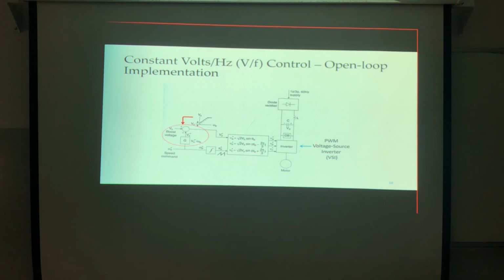With the actual output. We are giving a certain reference. Yeah? Now, if I need to control the inverter, I need to generate a reference signal. And any reference signal should contain what? V max reference and frequency reference, correct?